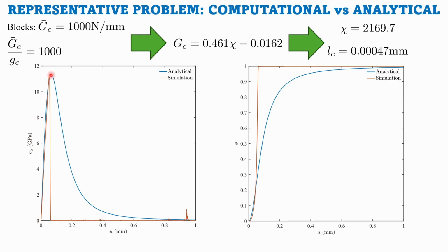The actual phase field simulation drops very vertically. Why? That's because the layer GC is 1, so it is very weak compared to the bulk GC. When you apply a displacement load, once it reaches the peak, it drastically drops, so the failure happens almost instantly. That's why you see this vertical sharp decline. But the stress at which it occurs is qualitatively the same.